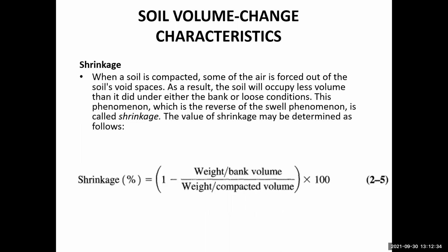Whereas the shrinkage we can consider in those situations when we are placing the loose soil into some final place of destination, for example in cut and fill type of calculations. When filling the soil at a construction site, we can consider the shrinkage factor. If we have a loose soil, we place that soil and then compact it with compactors. The volume of the soil will decrease and its unit weight will increase. In this way we can calculate the shrinkage. So not only the swell is considered, but the shrinkage is also considered.